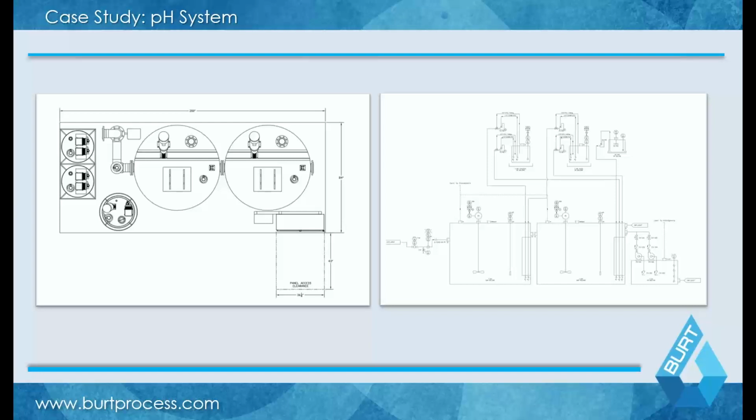Most people say you can generally move the pH about 2.5 to 3 pH units in a single pH stage. That being said, how you design that stage, as we're going to see in a couple minutes, does make a big difference, and you can do a lot of treatment in a single stage if it's designed for that purpose in mind.